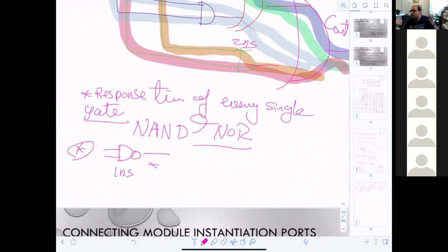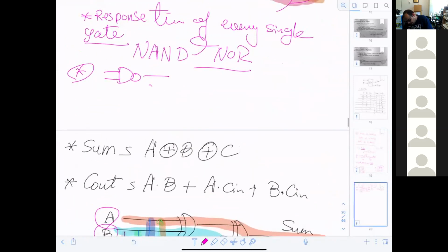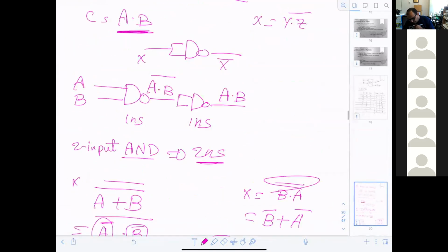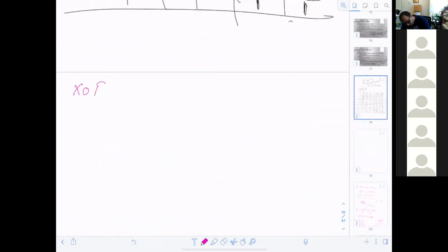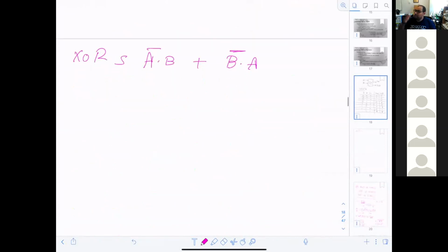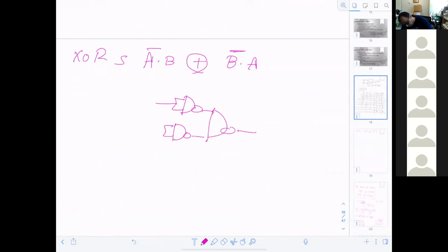Now we are coming into the funniest part, which is what? XOR, right? So in that case, we go and say XOR. What is the equation of the XOR? XOR is A B complement plus A complement B, like this, all right? Do you guys agree? I know my OR is like this. This is my OR, right? Then there are two branches. One is for this, one for this, right?